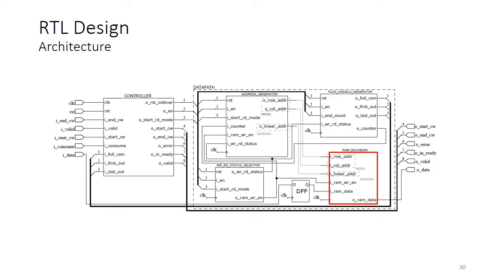For the interleaver, as the maximum number of lines is known, and the interleaver process follows column-wise direction during frame reception, it is possible to use a 2D memory to index rows and columns independently. This approach reduces the complexity of the address generator, since it demands only simple increment operations.